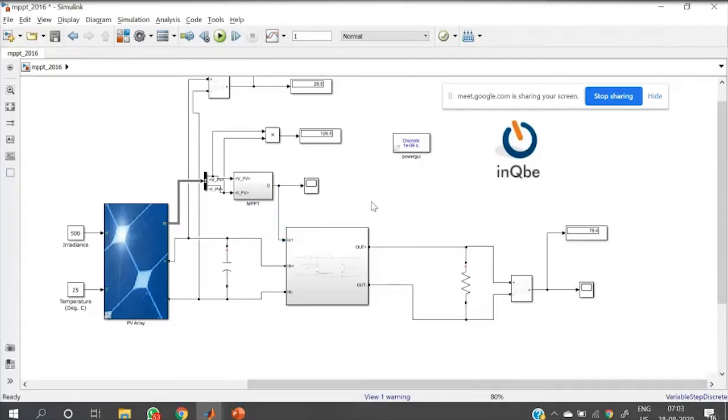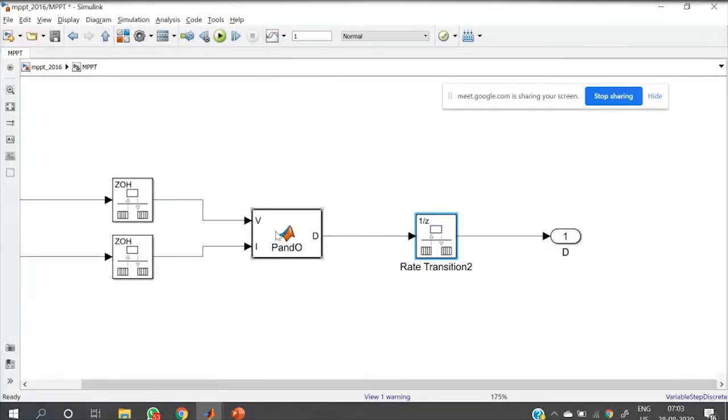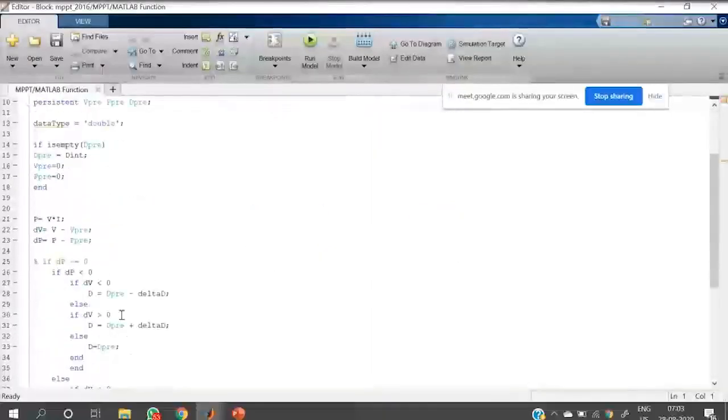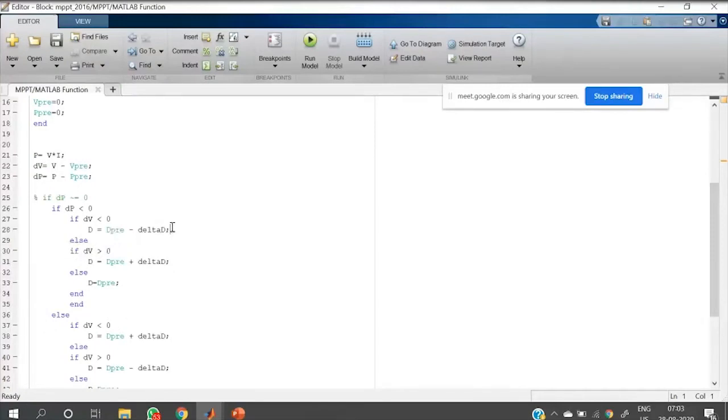Okay, for that indirect control, for controlling the input voltage, do you need one more converter? No. We have to apply a closed loop system only. The algorithm can be modified by changing duty cycle to voltage. We can update the relation here: for increasing voltage, there is decreasing duty cycle, so this sign should be varied.